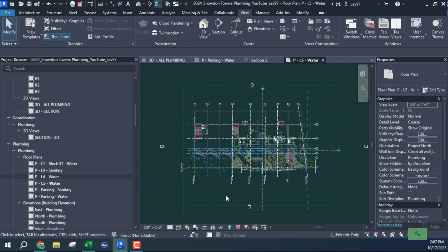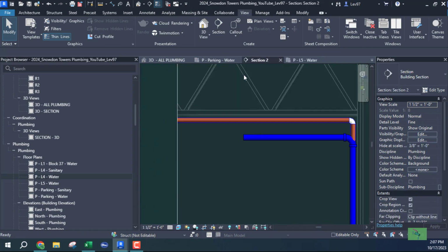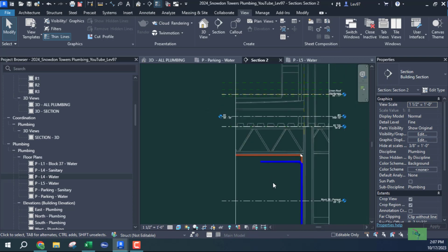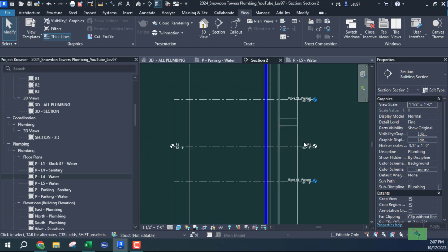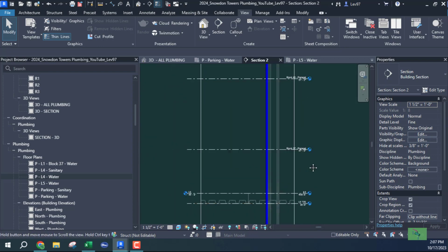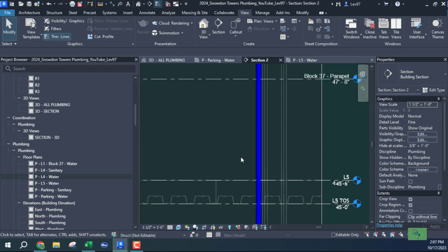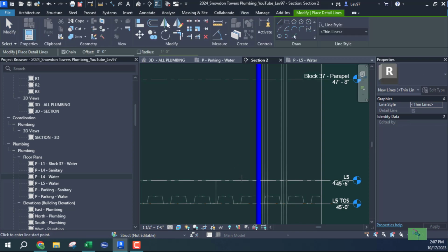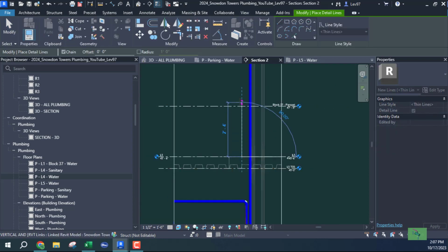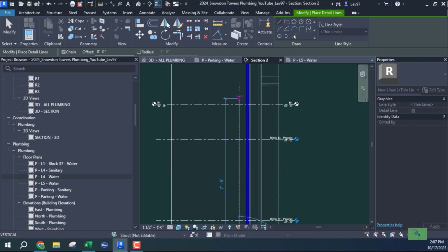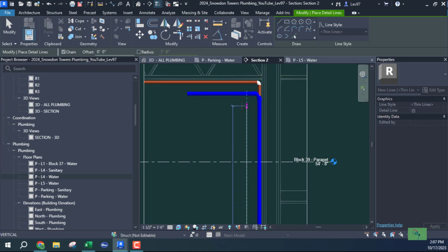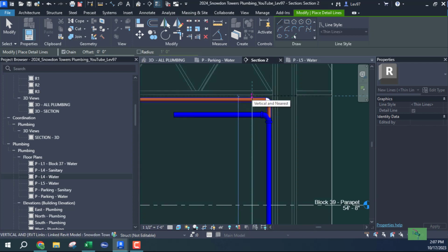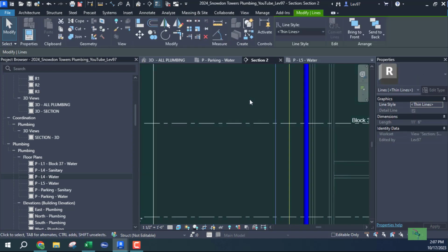Let's look at a view range. Let's go back to level 2 and look at the view range. It's R1. That's level 5. I'm going to draw a detail line for level 5, and we're going to go all the way up, 7 feet, 9 feet. Let's see how high this is.